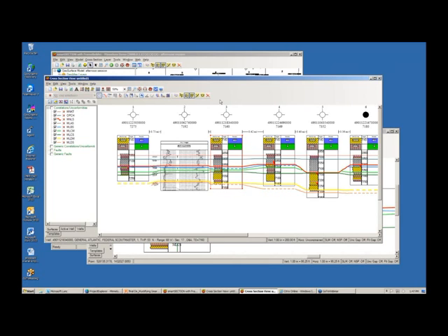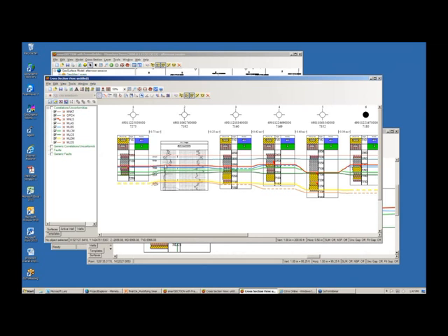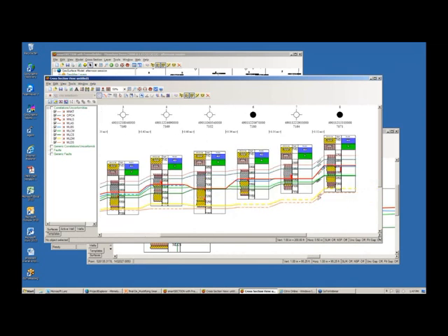Right. Let's see, there's a couple of more here. Maybe I could pick one of them out here. Once you've moved a log for correlation, maybe you've dragged it around, how do you put it back in its correct structural position? We just do a right mouse button, respace horizontally. No, structural, vertically, put it back structurally. Oh, you just control space bar. Perfect. We'll take it back to a structural image. And let's see if there's anything else here. Looks good for now. Okay.